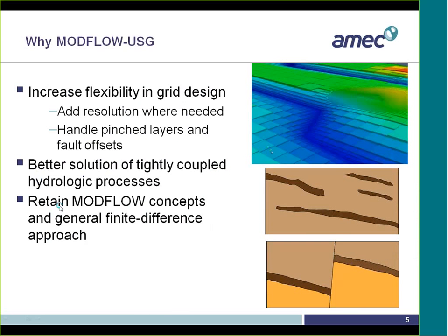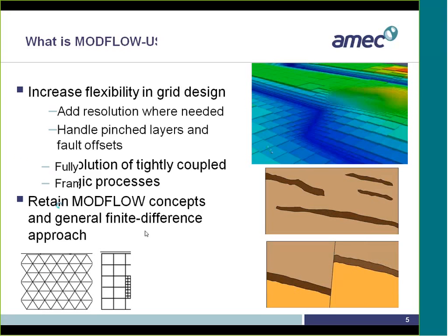So why MODFLOW-USG? We designed MODFLOW-USG initially to increase flexibility in grid design, add resolution where needed, handle pinched layers, handle things like offsets, and allow for better solution of tightly coupled hydrologic processes, while still retaining the MODFLOW concepts and the general finite difference approach.